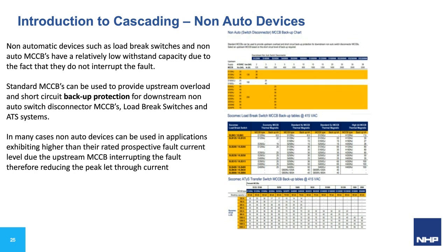Standard moulded case circuit breakers can be used to provide protection for the same construction non-auto models, as well as for certain isolators and for load break switches, etc. Moulded case circuit breakers can also be used very effectively where automatic transfer switches are being used that do not incorporate overload and short circuit protective functions. Coordination charts are published by most premier and tier 1 manufacturers and vendors.